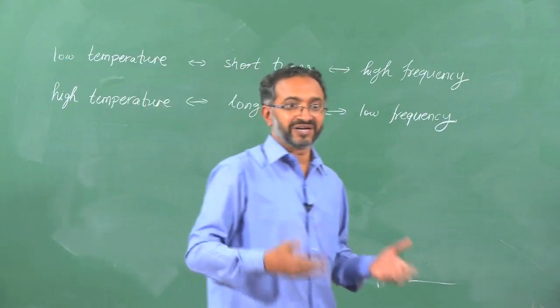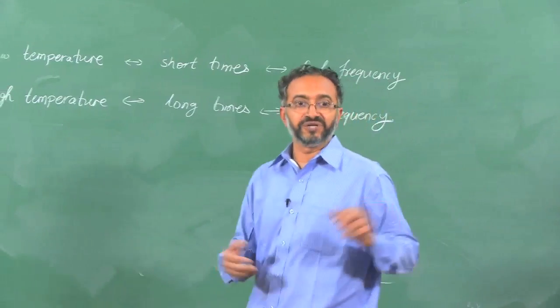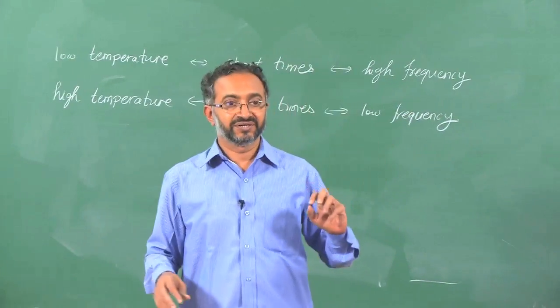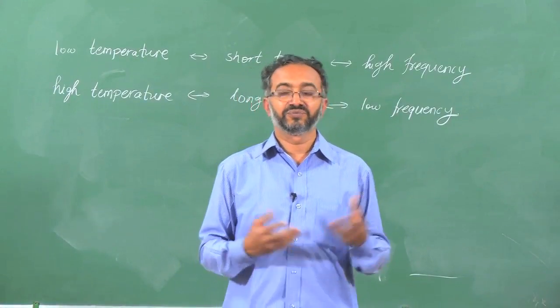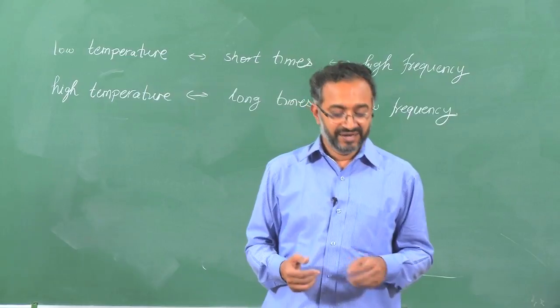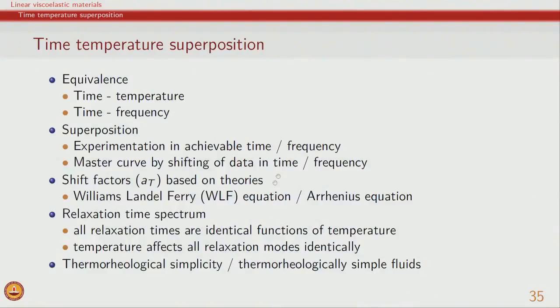So, no point in doing time temperature superposition. But let us say you get a master curve which appears to be quite continuous, then the next question is how much shifting was needed to construct the master curve. And in this case there are two sets of equations, or two sets of processes. If relaxation processes are of one kind, we get the WLF equation.